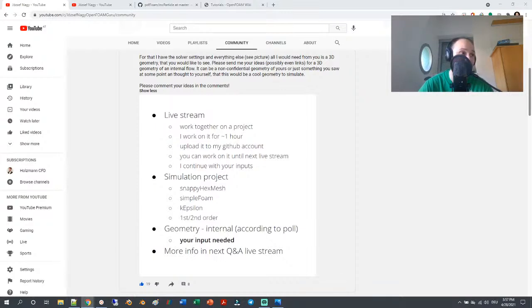How to choose T reference? That's the far-field temperature, usually. I'd have to see the case and also the error message for the wall heat transfer coefficient post-processing. So the T-ref is the far-field temperature behind the wall. Thank you for your answer.